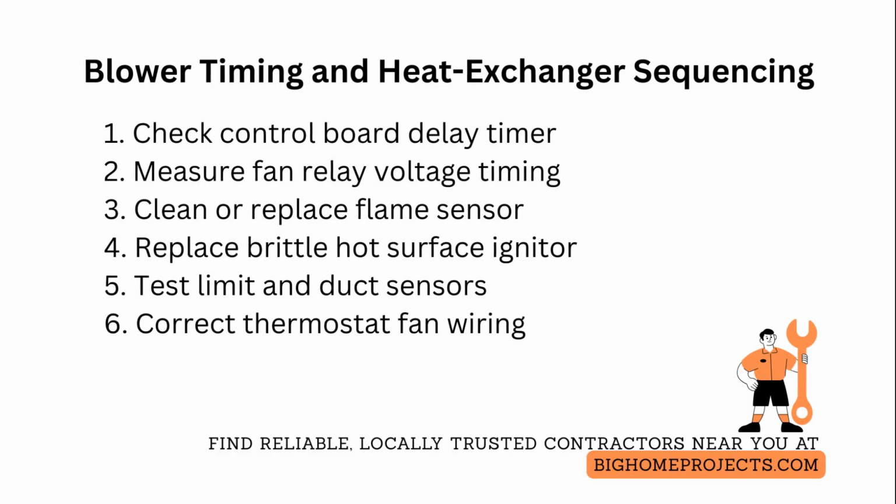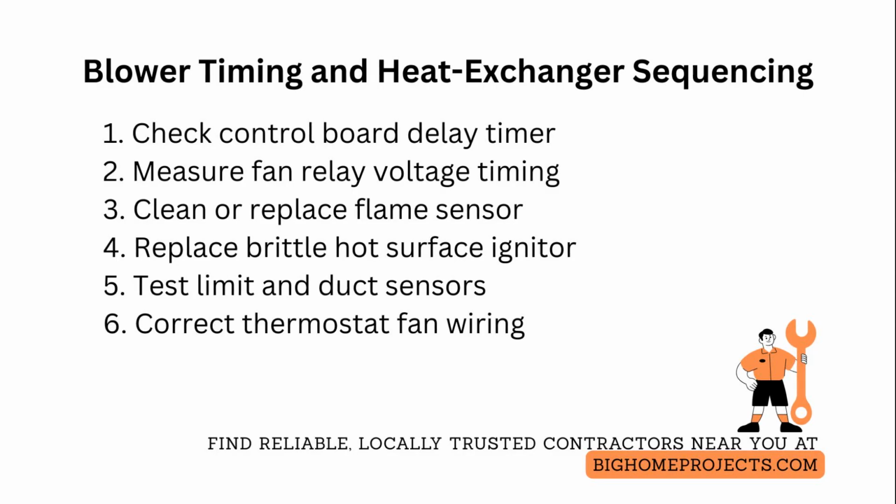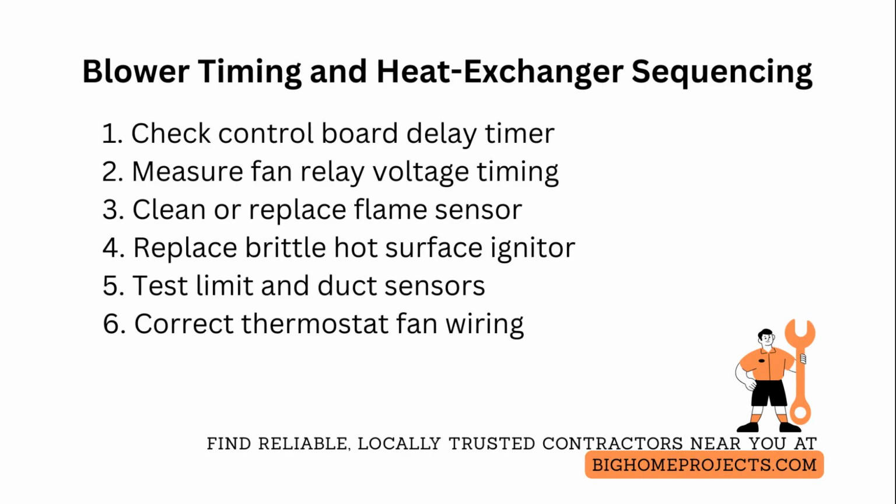Check thermostat wiring for incorrect fan control wiring. If the fan wire is tied to the wrong terminal or using a non-compatible programmable thermostat, it can command the blower independently. Move the fan conductor to the correct fan terminal and configure the thermostat to system heat mode only.